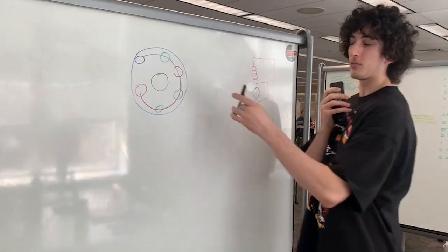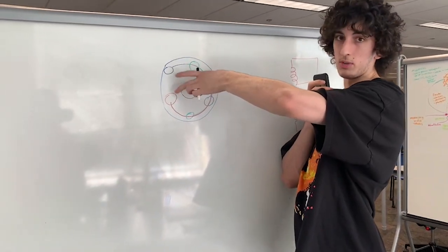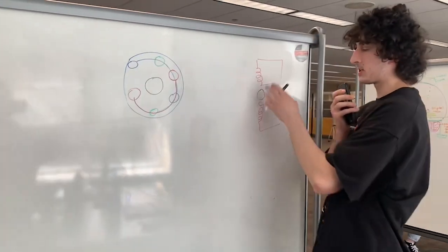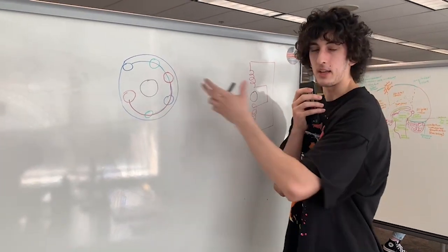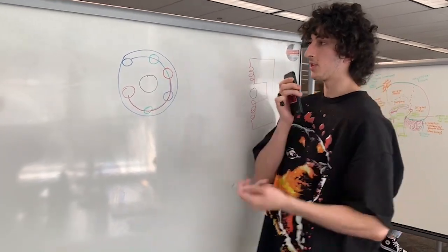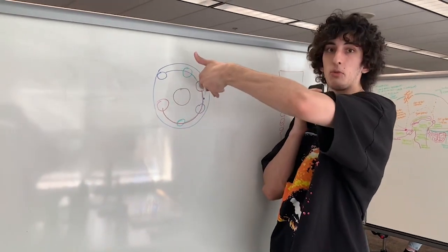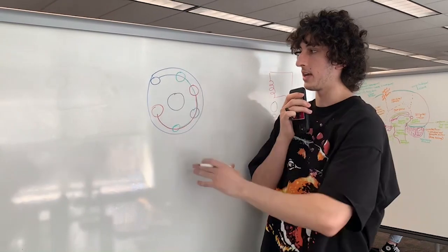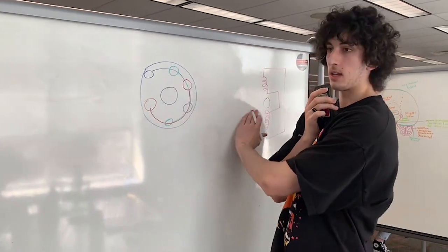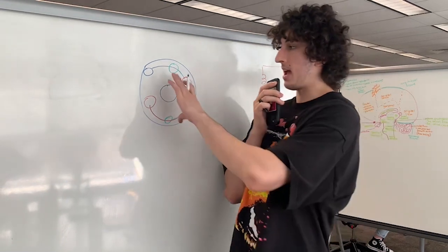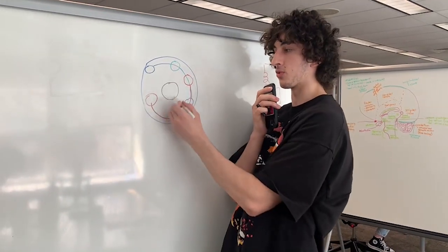Now, I say rotating because from this perspective, the magnetic fields are going to rotate like this. And in this perspective, the magnetic fields are just going to be switching polarity, but it's the same thing, just looking at it from different angles. So you have a magnetic field from the blue that'll go like this, and that will actually be changing polarity. And this is the beauty of induction motors, is that you can have something like this and model it as rotating magnetic fields. This is the stator, this is the rotor.